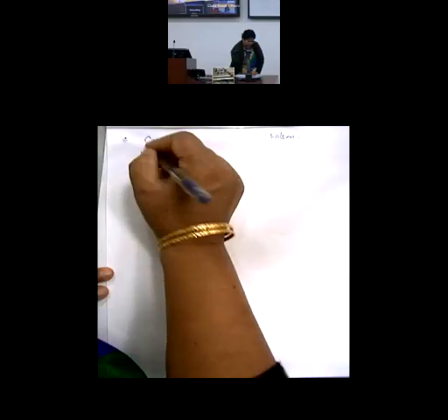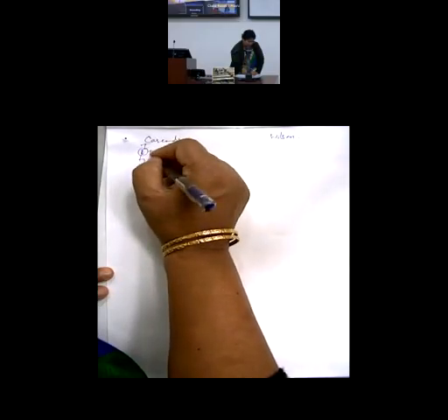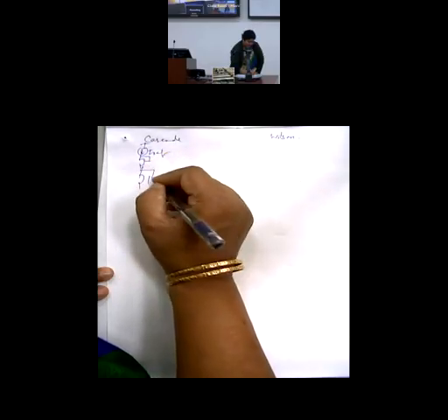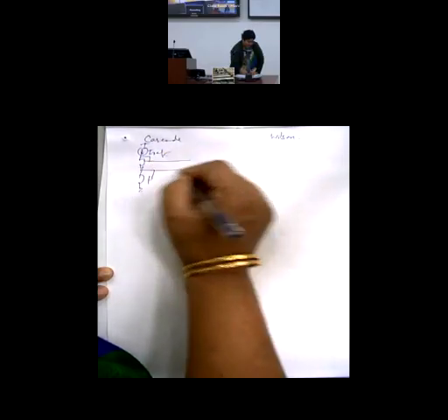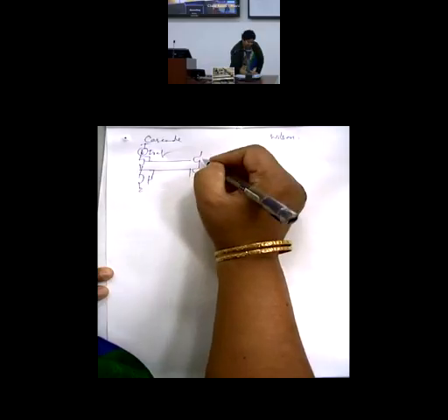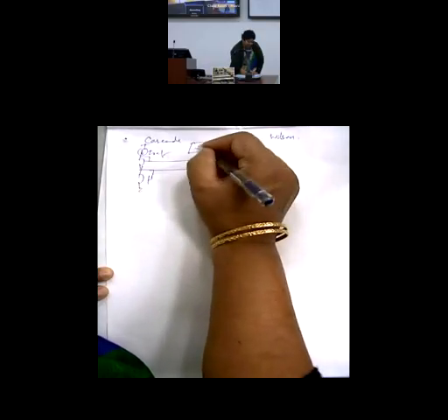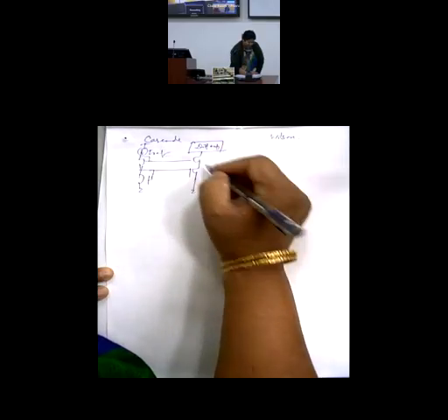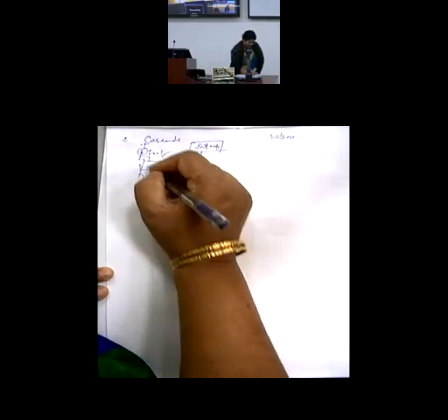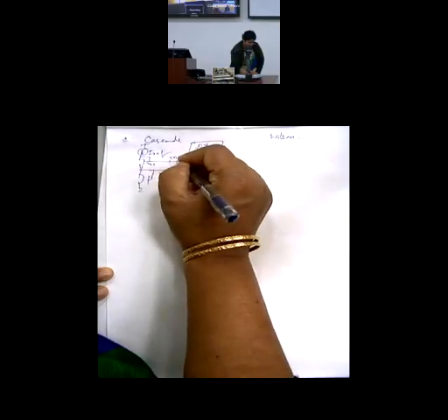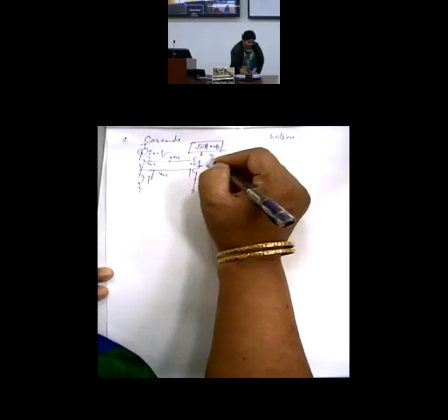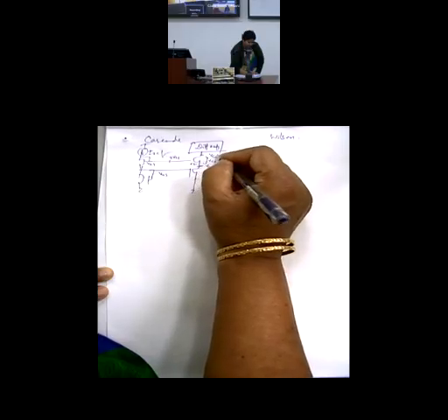Cascode means, I am drawing the NMOS configuration. This is cascode. And here you may connect your differential amplifier or any other amplifier. The minimum you require is VGS to VGS. This is also VGS, so this comes to VGS plus V overdrive. Minimum you require this much.